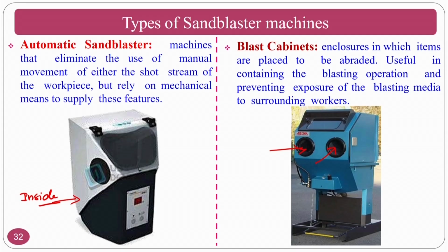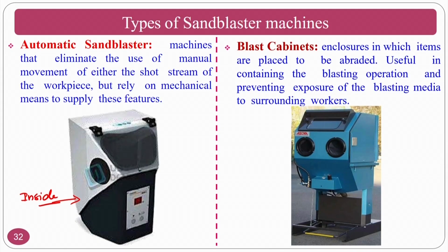Much more details I have talked about in the previous slides. The operator in these two cases is not directly exposed to the abrasive particles. There may be very minute exposure, but it will be very less. So, there won't be any problem from the point of health if you are using automatic sandblasters or blast cabinets.